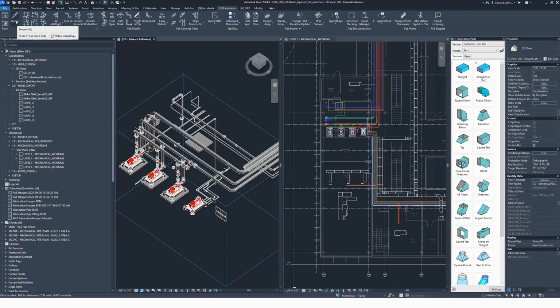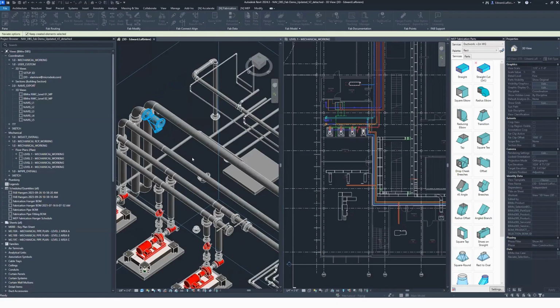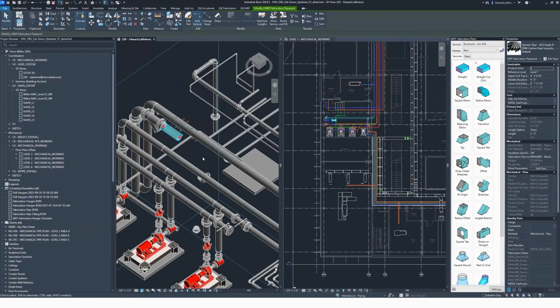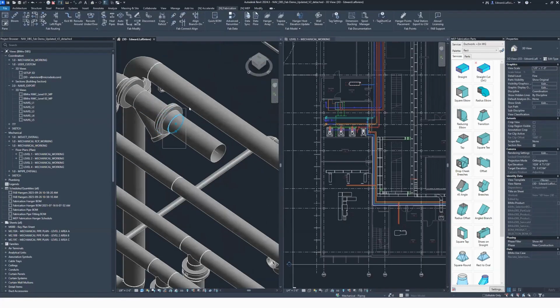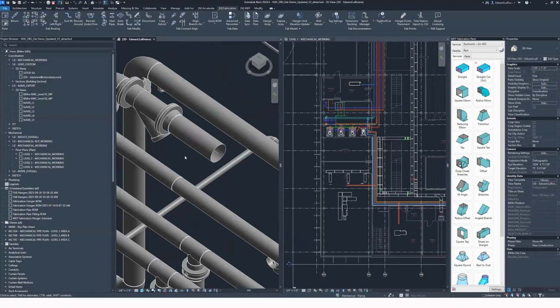This tool we have up here called Bloom. We'll see what Bloom lets me do is go right down to an element, choose that element, and it's going to go ahead and give me an extension coming directly out of that. So we get that straight showing up right here. Something pretty neat you'll catch: all these Naviate tools follow all those settings you've already got set up. Whatever you have in that properties palette, that's what we're running with.